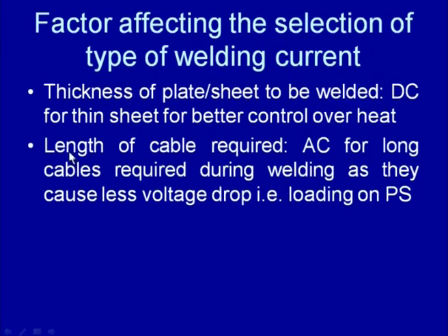Another factor, similarly, if you want to weld thick plates and we want to have more heat on the base metal side, then also DC is preferred, by using the straight polarity where more heat is generated in the base metal side.